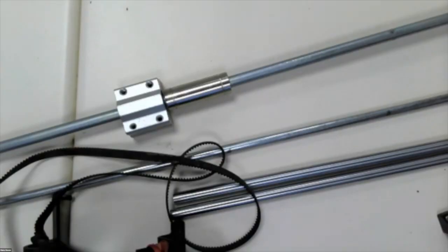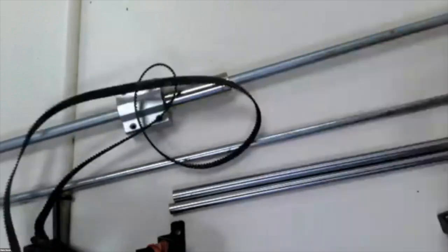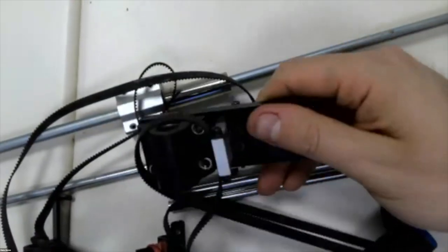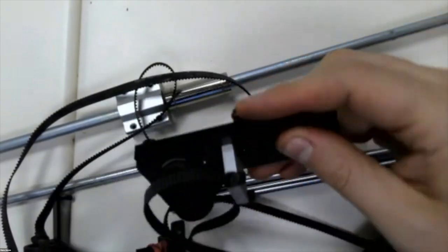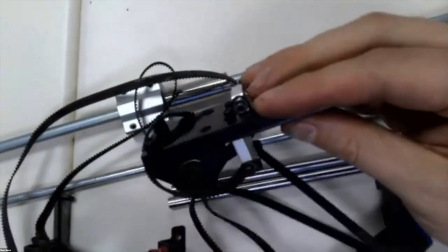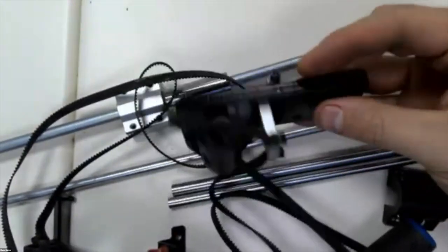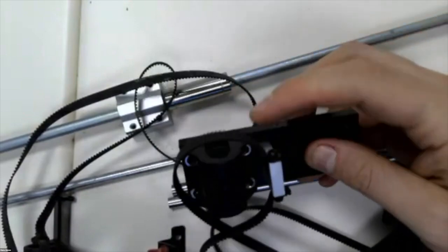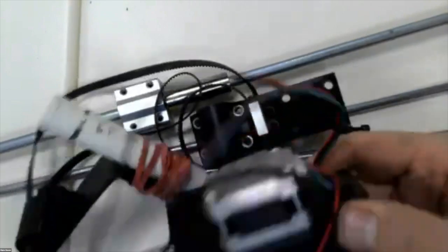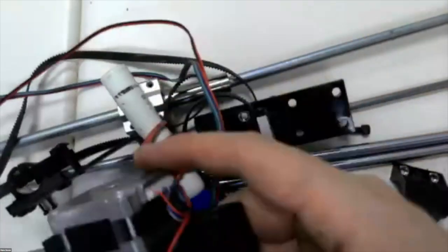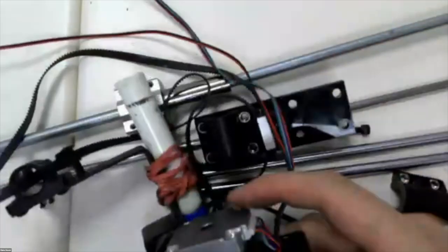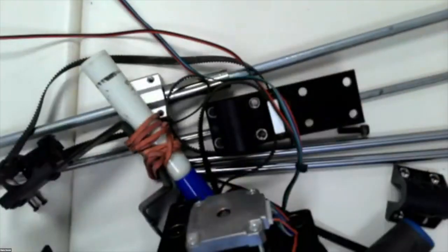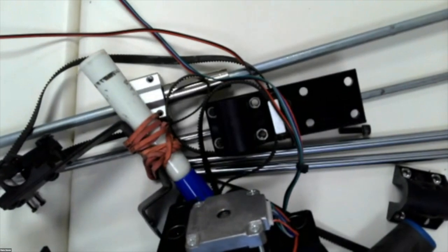The thing that is currently my picture on screen, and we'll look at this a bit more, but these are all belt drives. This right here is a belt, and the belt drive would be attached to some sort of a thing that slides along. You can see here there's a little linear bearing right in there. This would be drawn along the structure of the machine this way by the linear motion from the belt. A motor like this one turns, and as this motor spins and turns, it's able to slide this piece along its length. Ultimately, that's our belt drive. We're going to try and better understand it than this mess right here by looking at a few clean examples.